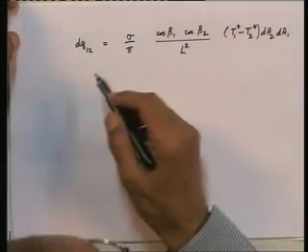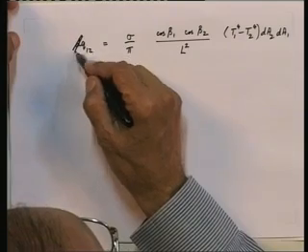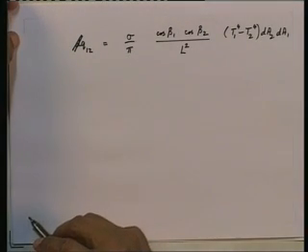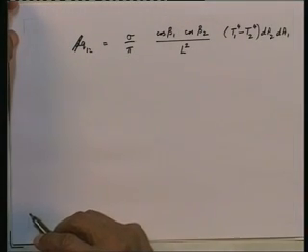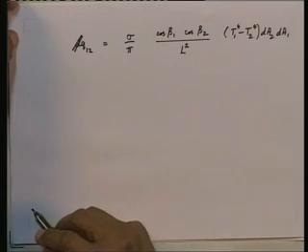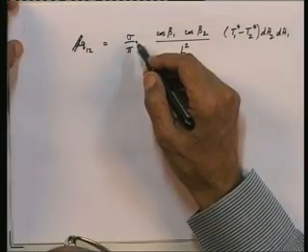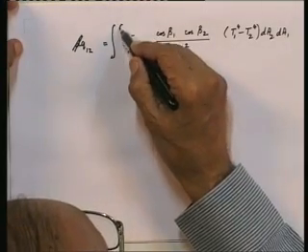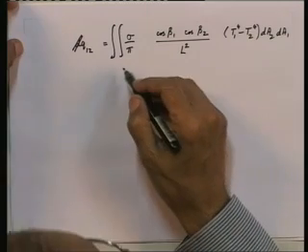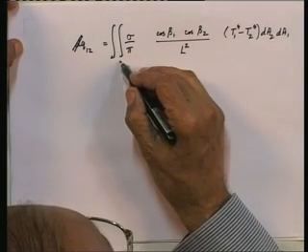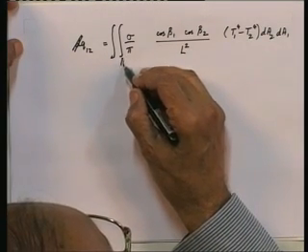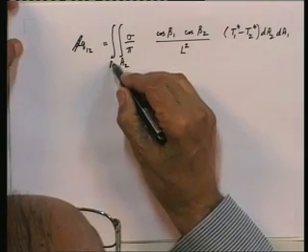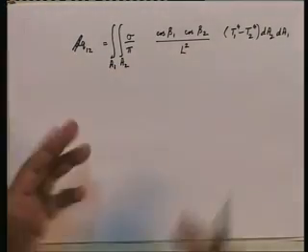If I want Q1 to 2, let me cancel out the d on this side. If I want Q1 to 2, that is the heat exchanged by radiation between A1 and A2, I will integrate this expression twice over the area A1 and A2. All right, that is what we will do, and that is our expression